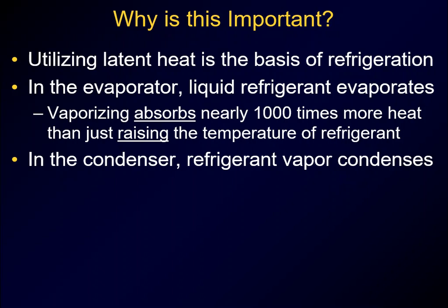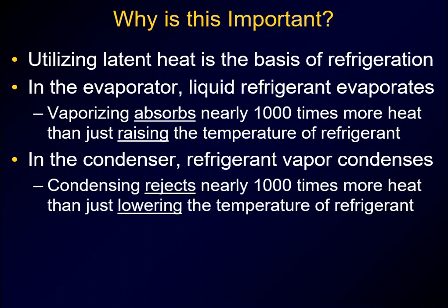work. In the condenser, refrigerant vapor condenses. Condensing rejects nearly 1,000 times more heat than just lowering the temperature of the refrigerant. So in the condenser, you're going to be rejecting heat, which is going to cause that refrigerant to cool off. But the cooling off isn't what does the work, it's the change of state.